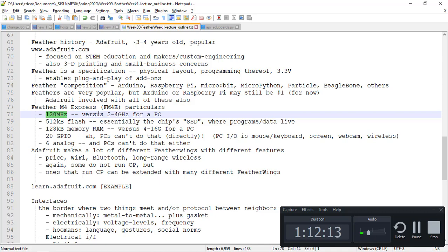So if you connect a very low resolution camera, which you can get, to a Feather, you can actually do some useful things. For an image sensor size of say maybe 128 by 128 or 256 by 128 pixels, you can do some reasonably interesting things. You can detect when somebody moves into the room, into the field of view and out. So you can follow what pixels have changed. But more than that, you're pushing the limits. So for the most part, video is a stretch for a processor like this, but a lot of audio is